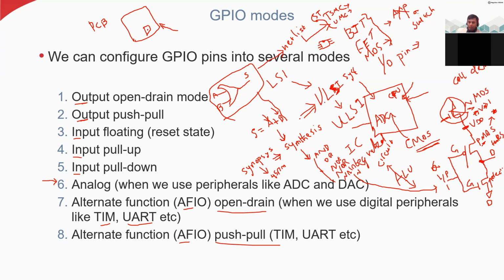Okay, so VLSI, please try to have some idea about this VLSI because you are going to graduate soon. As digital electronics students, you should know what digital electronics is. You have studied analog electronics in your course last year. Digital electronics is really based on this VLSI. As I told you, we can write this program using VHDL or Verilog. You write the program and do the synthesis, and then you will get the netlist, and then you will send it to the company, and they will fabricate it and so on.